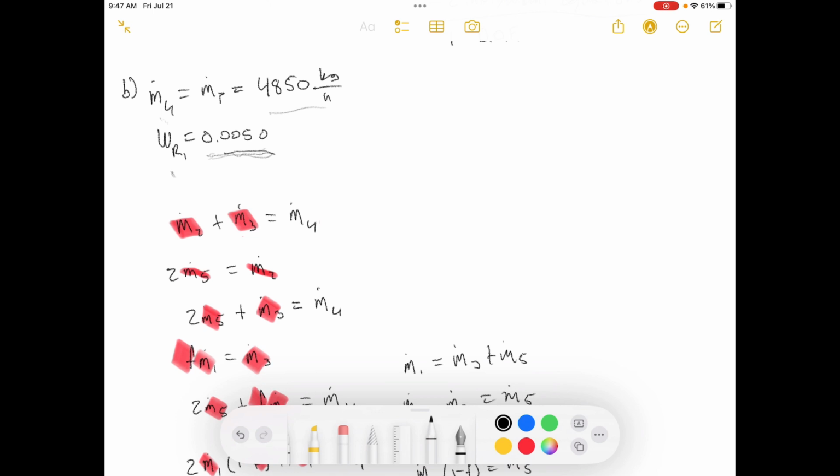You can solve what this is, but it doesn't actually make any sense, because in order to hit this small of a fraction going into the reactor, you would have to bypass your entire stream, or more than your entire stream. It's kind of out of bounds of this reaction. So you can specify this, but it makes no physical sense when you get it that low.